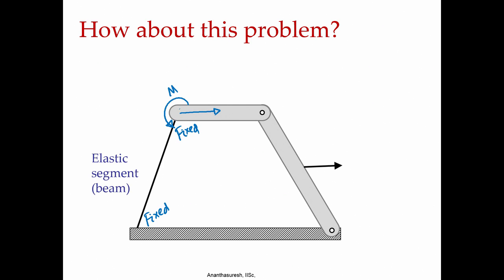So, we have force at this point which can be again resolved perpendicular and parallel. We have two components, transverse force and then axial force, but we will also have a moment. Since we do know how to handle transverse forces, axial forces and moments, we can actually deal with this beam, and hence we can actually solve this problem.